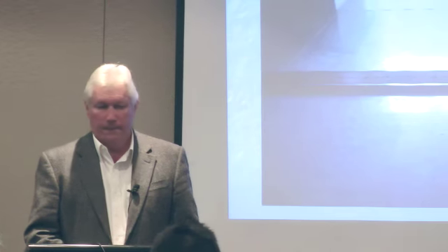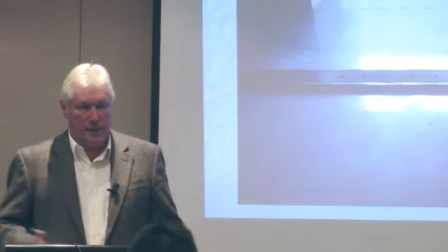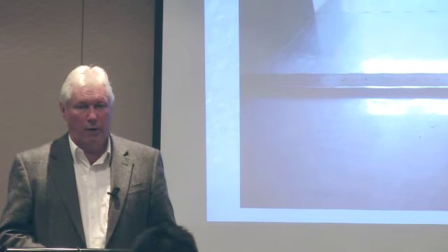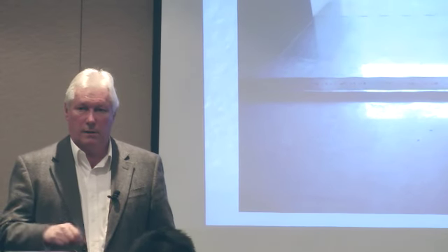We talked a little bit about dimensional stability, and in this case the tiles were laid in the mortar bed, and within a week I was there saying, well, what the hell's gone wrong? Because the edges were all drummy, but the middle was solid, and the tile has taken in water on the underside, curled up slightly, and broken the bond. So we tap the centre and it's solid, go to the edges and it's all hollow.